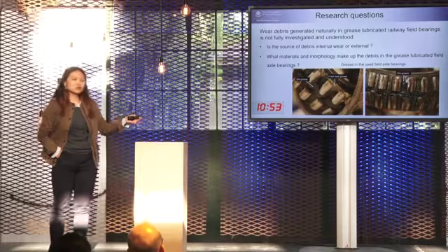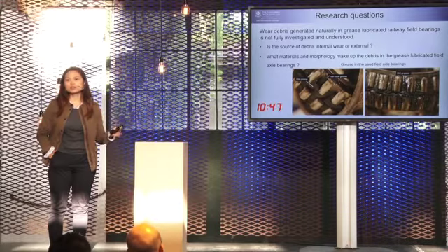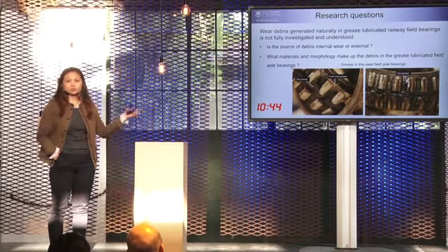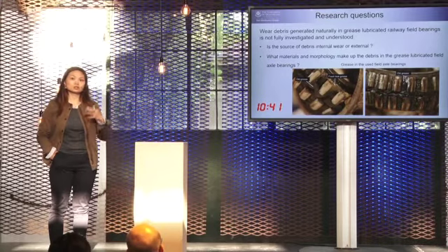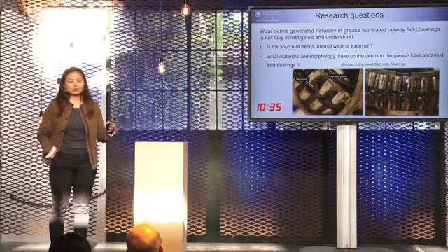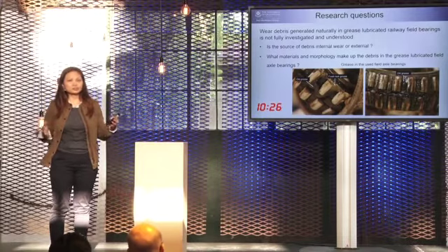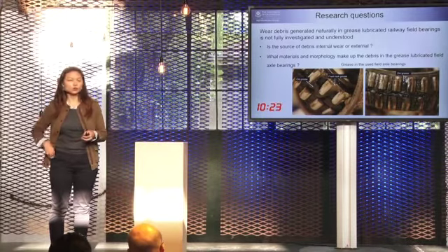What we found with previous studies is that 90% of them use wear debris analysis to look at bearing systems lubricated by oil. But we know that 90% of bearings are lubricated by grease, and there's a difference between grease and oil lubrication. In grease lubrication, we have additional additives and a metal thickener. So it's very reasonable to assume that the generation of wear debris found in a grease-lubricated bearing is more complicated than in the oil system.